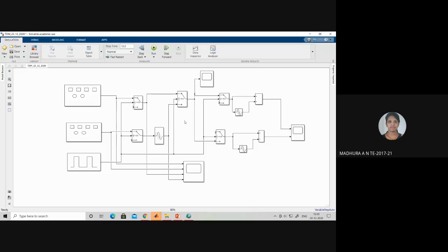Sir, the switch and transport delay are connected to the box, sir. Which one? Is that an adder or what? You see, the output of the second switch is connected to the transport delay. Then the output of the transport delay is connected to the third terminal of the third switch. Not this one, sir, the other side, the right-hand side. Yes, sir, this is for recovery.